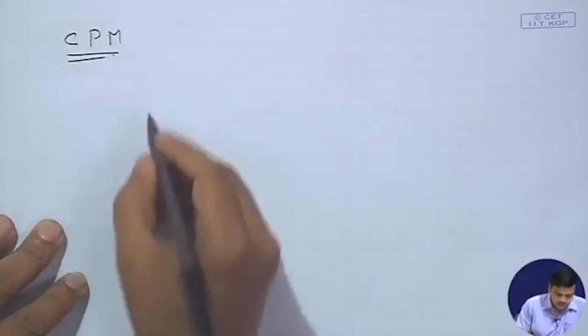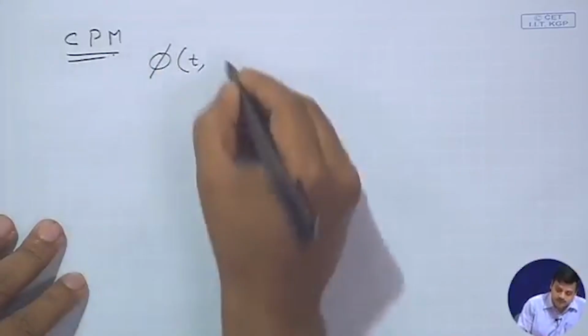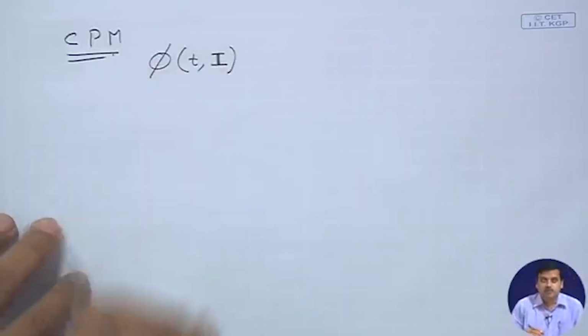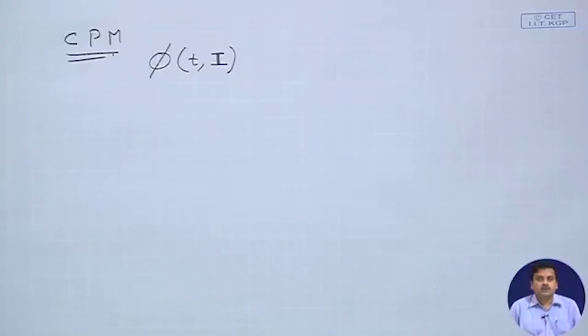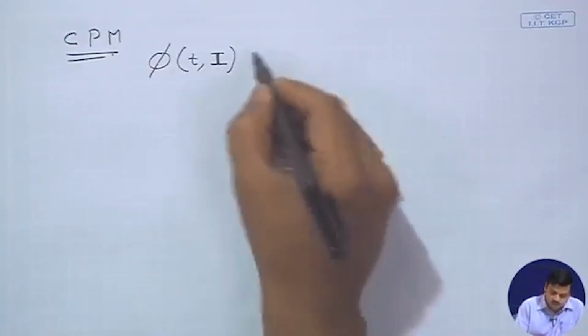So, when we look at a continuous phase modulated signal, in this case the phase is a function of time and the input data sequence set. So, when I write it in bold, I mean it is a function of not only the instantaneous signal, but it is also a function of several incoming sequences, which is all the past history. So, that is why we have this I n over here.